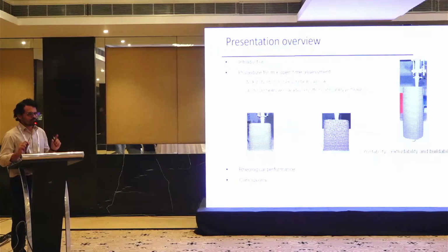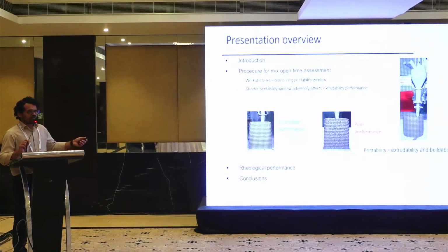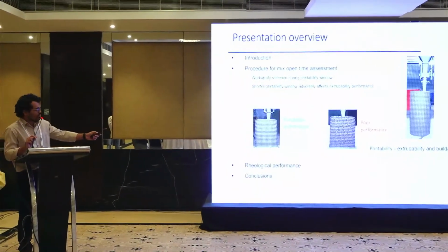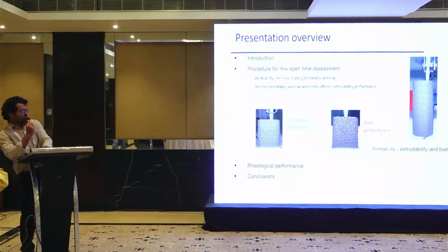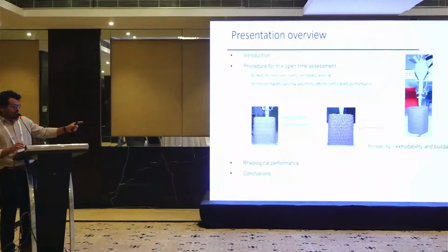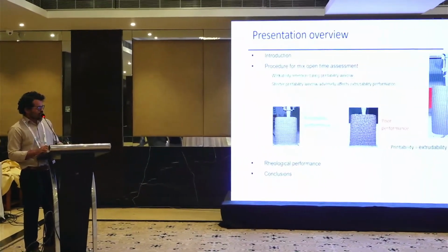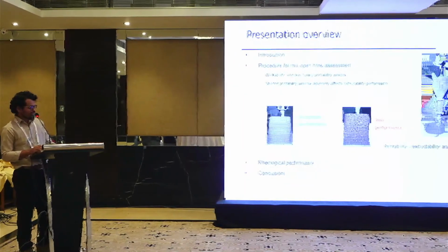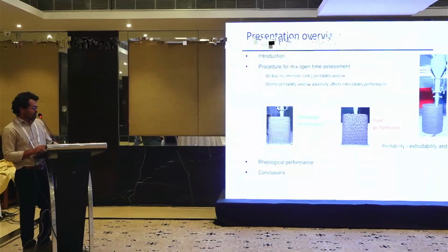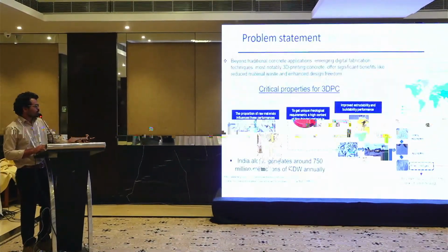Open time is the duration during which you are able to extrude the material without any surface defect. If there is a shorter printability window, it results in a rougher surface texture. Here, in printability, I use extrudability and buildability, and I will use this definition in the rest of the presentation. Then I'll talk about the rheological performance, and then the conclusion.